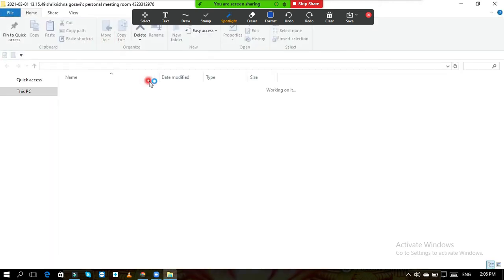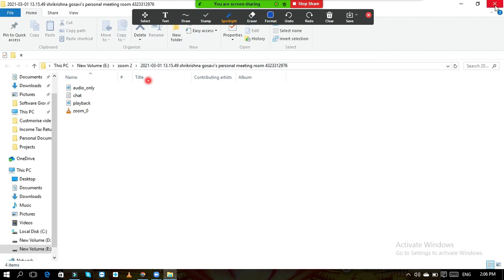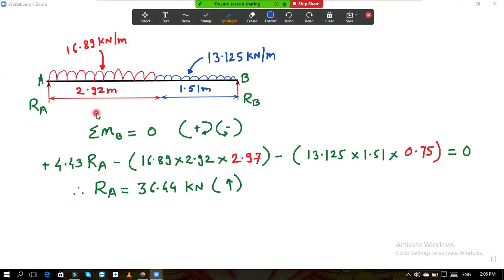So now this is not the case. Okay, now the case is different. Now here we want to find out the point where the bending moment is maximum. The point of contraflexure is the point where bending moment is zero, not the maximum. Okay, and so what we will do now,